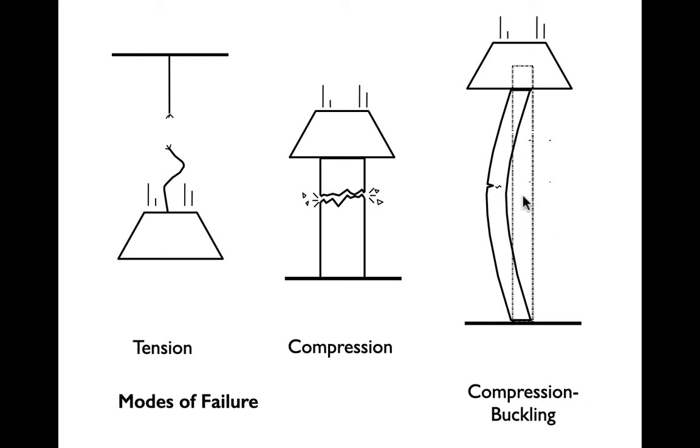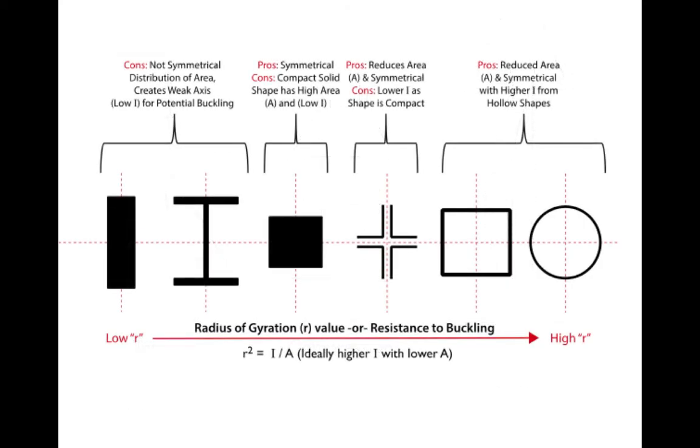These really, if we want to get technical about it, are beam columns because they are carrying not only an axial load, but also a bending load. And once that deflection starts, the moment gets bigger and bigger as the deflection gets greater. Greater moment causes greater deflection, and we end up with a vicious cycle where eventually the column collapses.